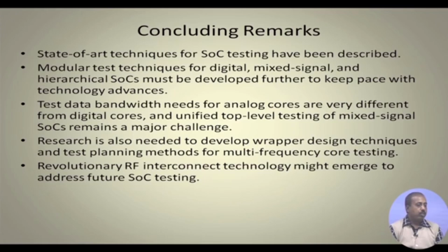So, coming to the concluding remarks. State of the art techniques for SOC testing we have seen. We have seen that modular test techniques for digital cores can be developed so that they can be integrated with this SOC testing mechanism. Test data bandwidth needs for analog cores are very different from digital cores, and unified top level testing of mixed signal SOCs remains a major challenge. As I said, analog testing is a challenge, and that continues here also.